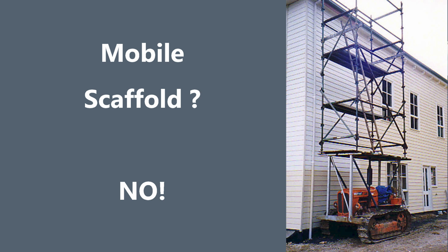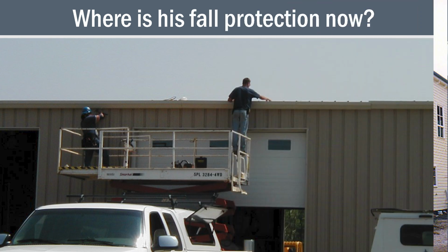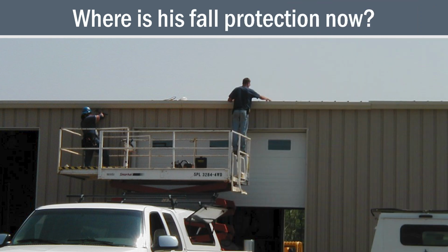All right. Now let's look at this next picture. The lady had a question a while ago. See where this person got above the handrail? He has no fall prevention or fall protection. That's the point. You say, Ronnie, how can people do this? Like I said, either they don't know, they don't care, they don't have any training, or they're not being supervised.